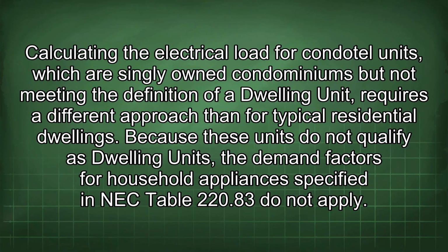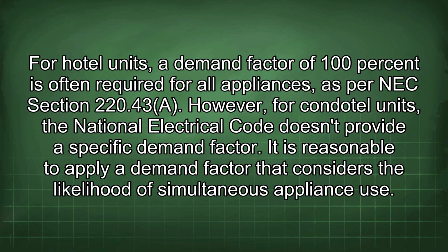Calculating the electrical load for Condotel units, which are singly owned condominiums but not meeting the definition of a dwelling unit, requires a different approach than for typical residential dwellings. Because these units do not qualify as dwelling units, the demand factors for household appliances specified in NEC Table 220.83 do not apply. For hotel units, a demand factor of 100% is often required for all appliances, as per NEC Section